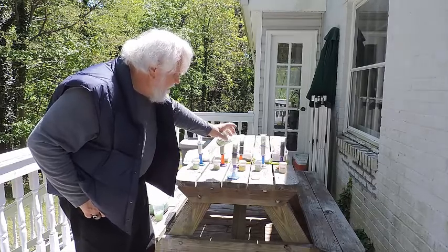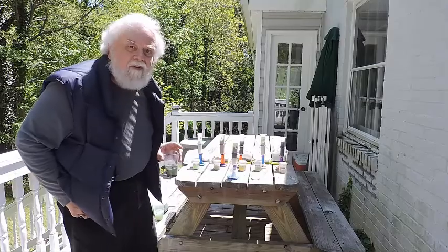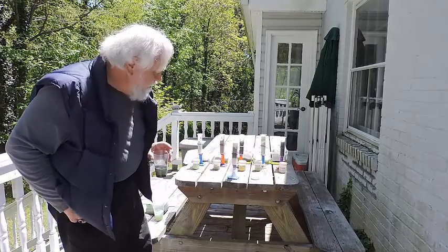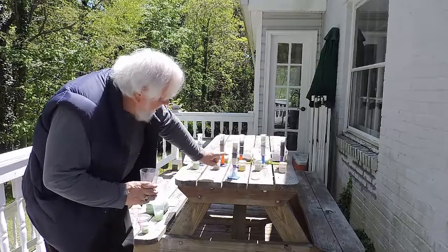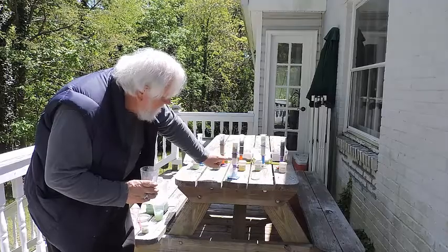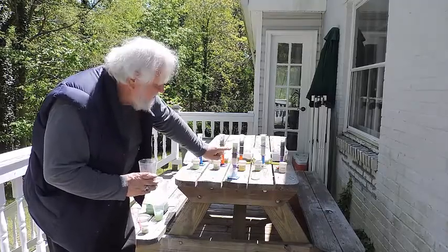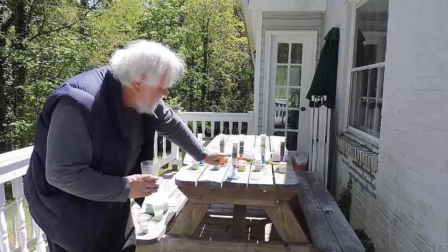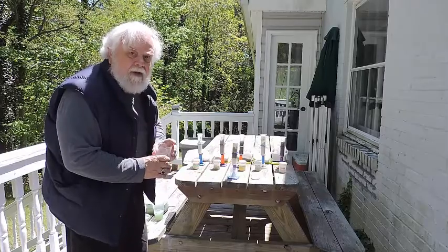Okay, I'm going to keep this as high as I can, because the bigger the column of water, the heavier the weight of that water, and the faster it will force the water to go through. So you probably can't see it from there, but the water level is down to about here. It's soaked to about there, and it's working its way down through the carbon layer. It's completely through the sand layer. It's working its way down through the carbon layer, and it will get into the cotton layers.